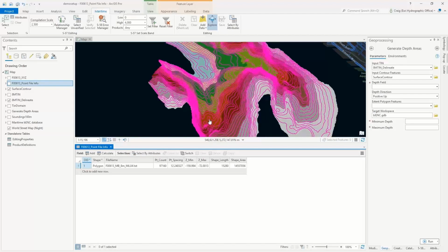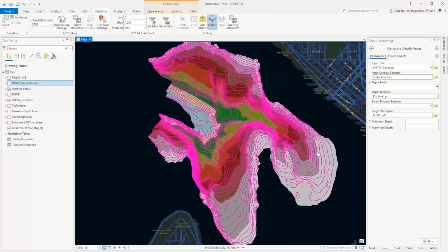If you have an isolated contour like this and it's searching, it finds that it's deeper, let's say. No, it's not shoaling, it's deepening. And if this was deeper, if your depth value range was deeper than 159, it would pull the value from here. So it's asking, what should that value be for that depth area? So you define those two, which are probably not going to be exactly what you got out of the point file information tool. I hope that made sense.